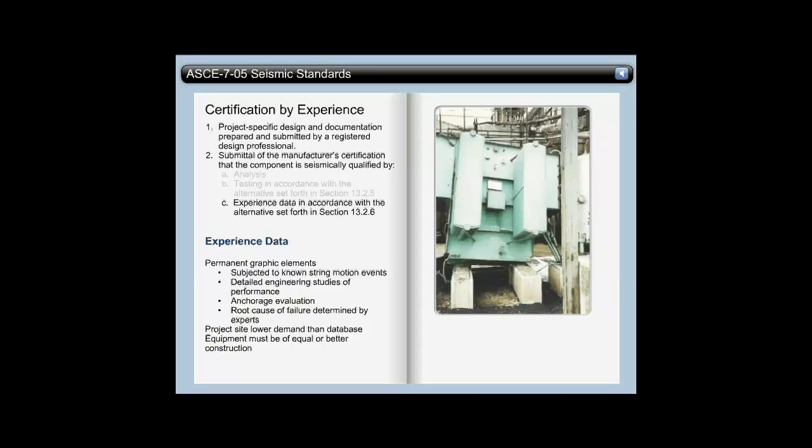By experience means that an existing equipment installation would be similar in nature to the new equipment installation, has a history of documentation proving that the equipment has been through similar seismic events that match the criteria of the new installation, is anchored in a similar fashion as proposed, that the performance over time has been evaluated by accepted engineering practices, and that if any failure has occurred, the root cause of that failure has been determined by experts based upon the chronological documentation.